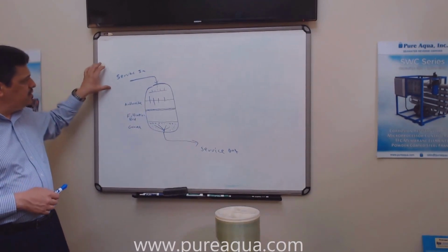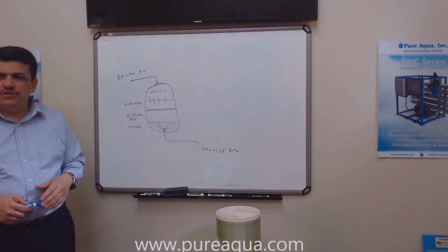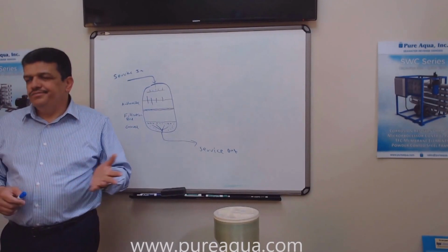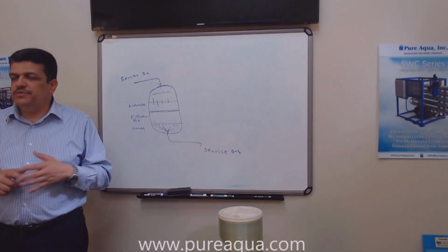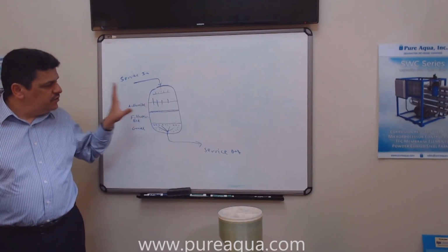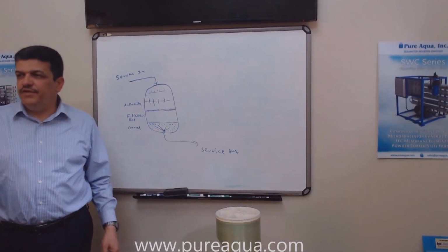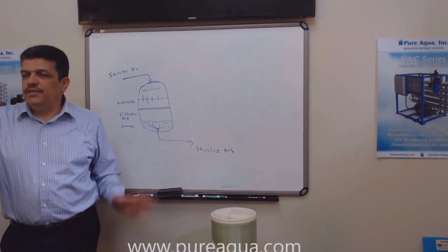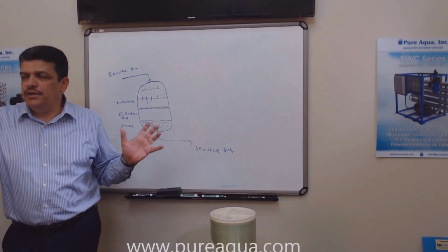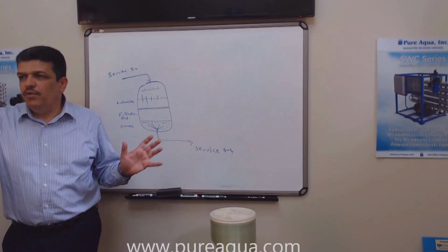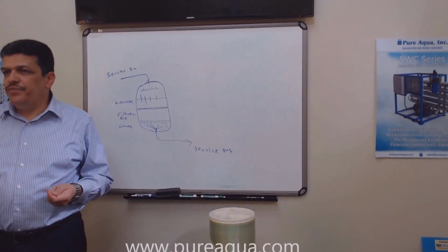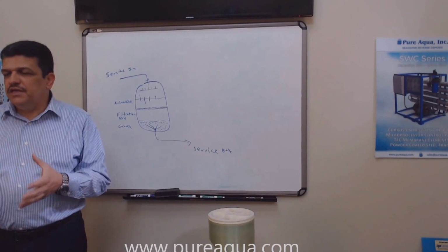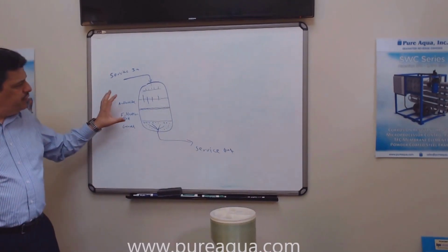Again, if the water is oxidized, this is also a good solution to remove a few amounts of iron, manganese. It removes turbidity, suspended solids, like we said. So this is the main benefit of having the media filter, or the dual layer or multimedia filters. Now, if the water is really, really horrible in the process that we are doing, there is something we call a multimedia filter.